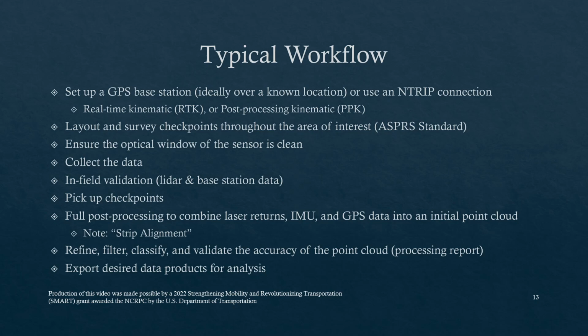Thinking about the layout and survey of checkpoints, so these are your validation points throughout your area of interest. You can look towards the ASPRS standard for this, but many operators don't follow that standard because it's pretty intensive. It requires 20 plus checkpoints. Most operators aren't going to do that much. They're typically comfortable with 6 to 10. That's really up to your own departments and how much effort you want to put into these validation points.